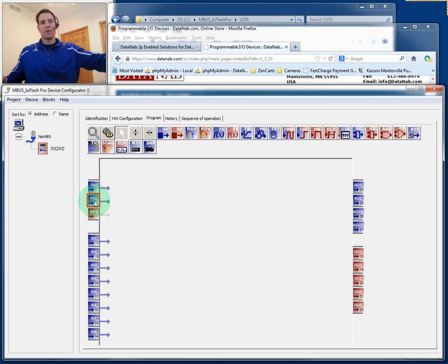The PCL is the photo sensor, the light level sensor, and we can use the value coming from that in the program. And then the MPB is the push button, which we can wire in to trigger things in our program as well. So that's what those three items are for. The MBus IO10 LCD G2 would not have this PCL or this MPB inputs because it doesn't have the push button or the photo sensor, the light sensor.